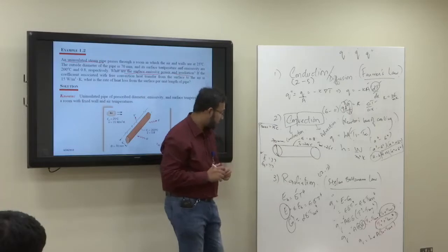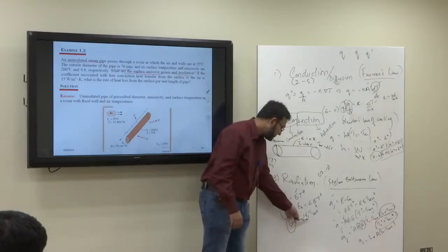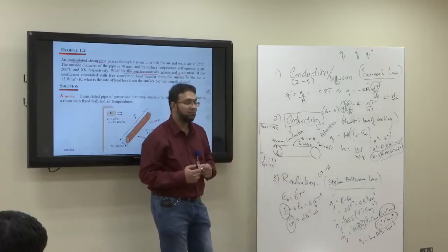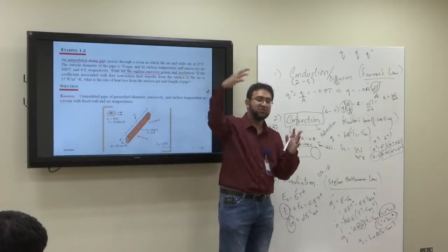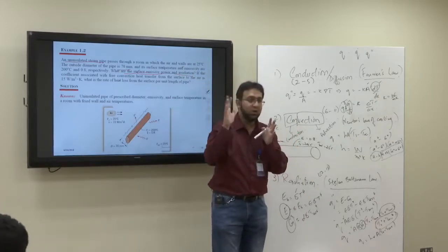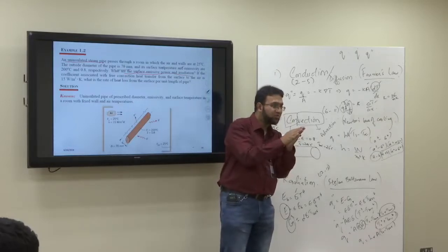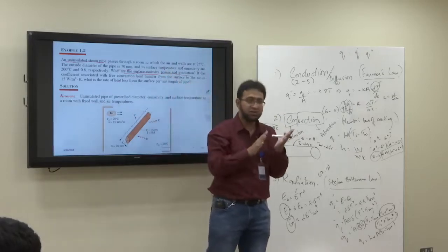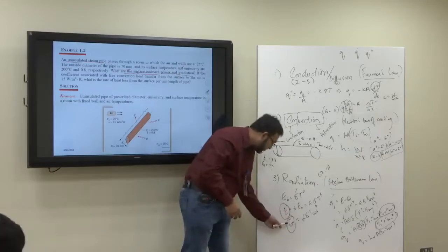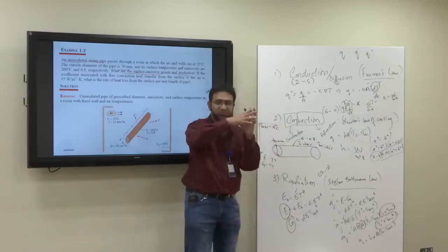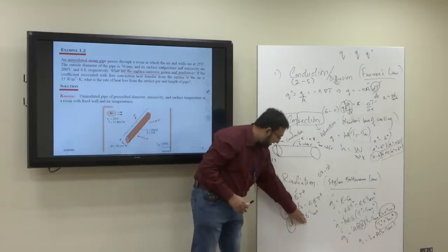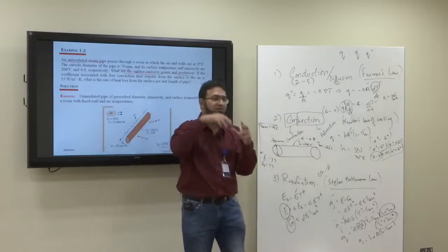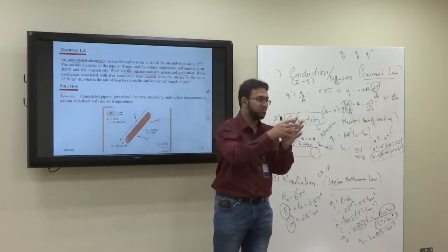What is irradiation? Okay, you have to understand one thing. One thing is how much is the amount of energy incident coming, then how much is the amount of energy absorbed. There are two different things. Suppose 100% energy is coming, but not necessarily all 100% absorbed, maybe 80% absorbed. So this absorptivity, when we use alpha G, depends upon how much energy is absorbed. But irradiation is without alpha. Alpha is the absorptivity. 100% was coming, alpha let's say is 0.8, that means 80% absorbed.